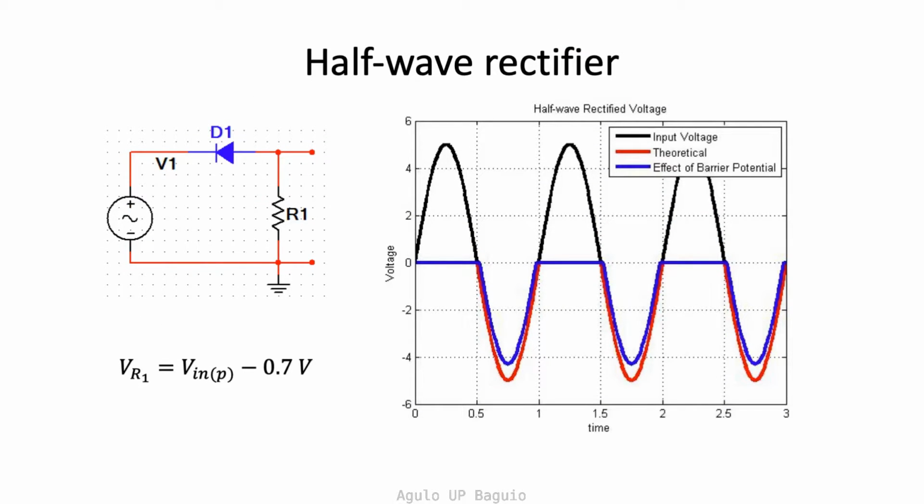When the orientation of the diode is reversed, then in the forward bias region, there is no current. In the negative region of the voltage, or in the reverse bias mode, the diode allows the passage of the current. Thus, current is present when voltage is negative. This is evidenced by the red and blue curves in the figure, which represent the output from an ideal diode versus the non-ideal diode or complete diode, respectively. The amplitude of the voltage is the same as in the other half-wave rectifier, except that the voltage is negative.